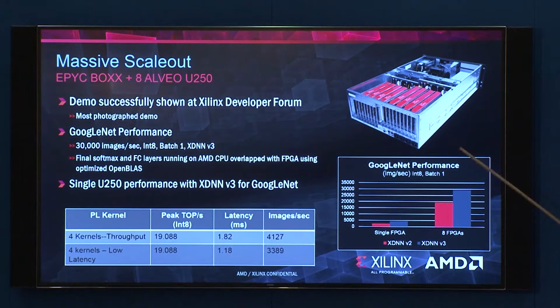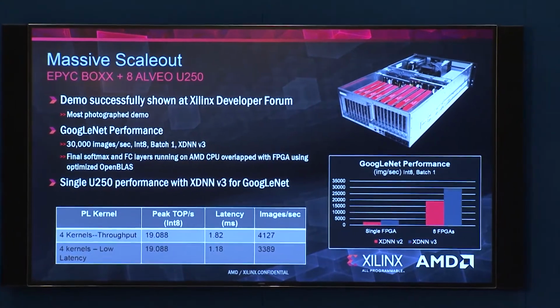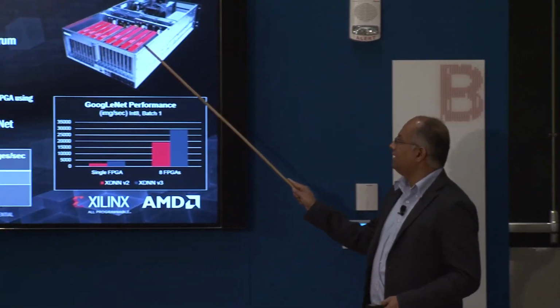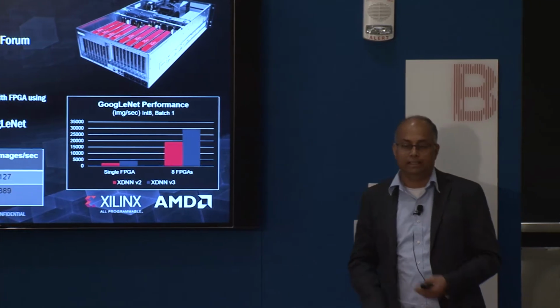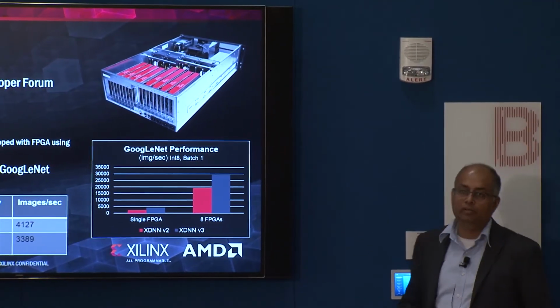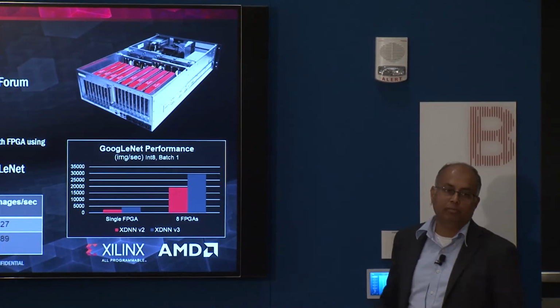This particular platform is really interesting. It is an interesting result from the point of view of batch 1: you can get high throughput, with so much data being looked at. But if you count the total number of lookup tables, it is more than around 10 million lookup tables, and 12,000 times 8, around 100,000 DSPs. Given that these are connected to the CPU in an interesting way, and AMD is pushing for that, you can really build more complicated data flow.